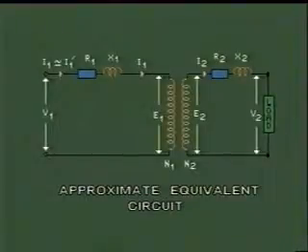In this process we have made an approximation to the tune of 3 to 5%. As you know, the no load current of a transformer is about 3 to 5%. Now in this diagram you see that I1 is approximately equal to I1 dash, as I0 is taken as negligible.